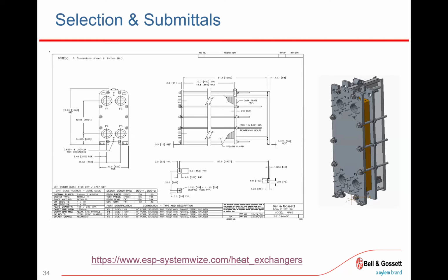So, single wall versus double wall. If you wanted to have an air gap in between, let's say there's a hole in the heat exchanger, rather than high pressure leading to low pressure, whichever side that is, if you have that air gap, it's able to run out and doesn't actually penetrate to the other side. So especially if you have anything that's toxic, or anything that's critical, but one thing to keep in mind with that really is that as we put that air gap in between,